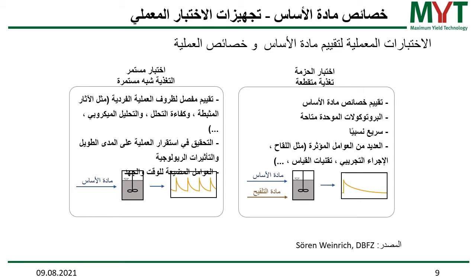Second, the more common, faster and cheaper test is the batch test. Here you set up a simple inoculum with your specific substrate. You are done after usually 30 days, and you can quickly evaluate the gas potential based on such a test. There are standardized protocols available, and such a test is much faster than the continuous test.